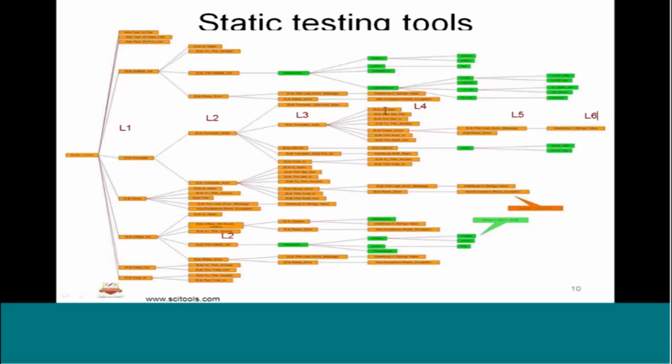So the complexity here we can presumably say is level 6. Of course it depends on each function and its internal details, and it will highlight with different colors different aspects of the control flow. So this is one of the good examples of the understand for C++ call tree. With the help of this, the user or tester can analyze how each program or function has been architected, and how each function or the individual procedures have been called within the entire embedded system. So this is a very important aspect for static analysis.